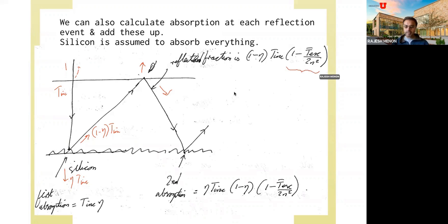If you remember, this actually comes from Snell's law, where T bar escape is just a normalization term. Let's not worry about this for the time being. I'll come back to this point later on. But really, it depends on 1 minus 1 over 2n squared times T bar escape. Now, this n is the refractive index of the PMMA that we're talking about. So this represents the total internal reflection that should ideally happen here.